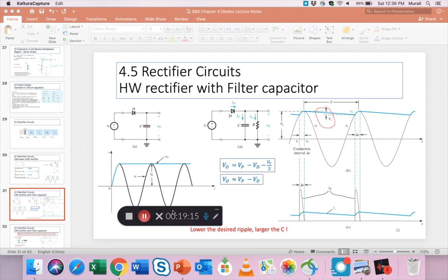So you see how the capacitor goes through a charging cycle and then a discharging cycle when the AC waveform is on a falling trend. When the AC waveform is rising, at a certain point it starts to charge the capacitor, and then when it starts to fall, the capacitor starts to discharge into the load.